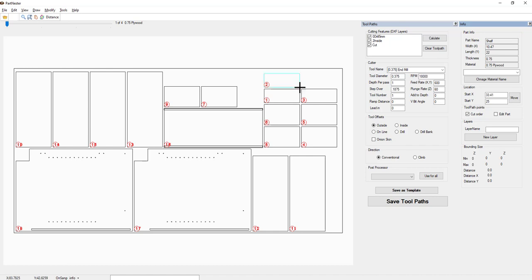So the way we'd want to have this done is starting with the smallest part, thinking that if we had the plunge point here in this lower right corner of this part, that's where we would want to make the initial plunge as it goes up, over, and comes down. The part is still attached to the bigger section of the material while it's making its last cut through.